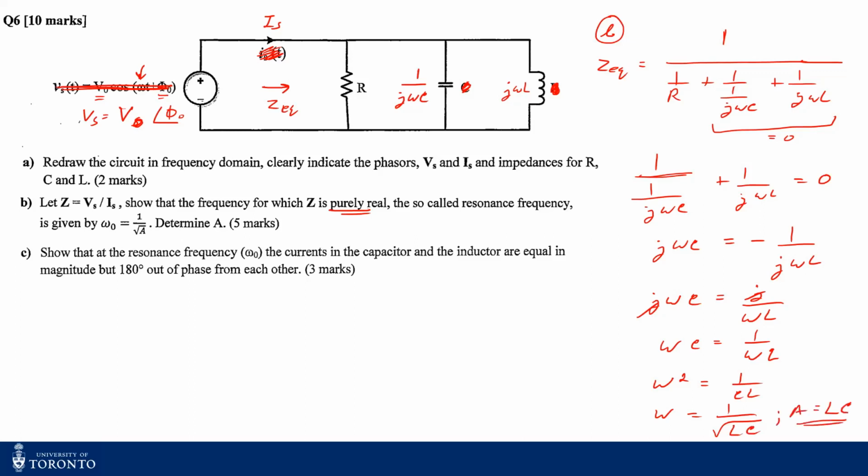So this is the resonant condition, and the frequency at resonance is omega naught for this particular value. And for this particular value, your Z equivalent will be a real value, only resistance. The reactance of the capacitor and the inductor will cancel out, and this omega naught condition will only exist if there is an inductor with a positive reactance canceling out the capacitor reactance, which is negative. You cannot have omega naught for only a capacitive system or only an inductive system.